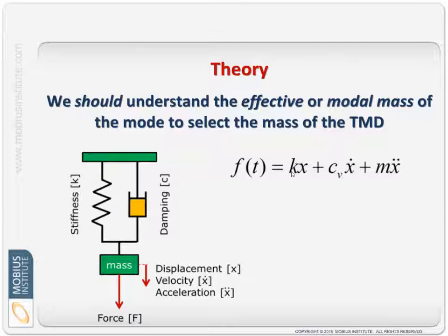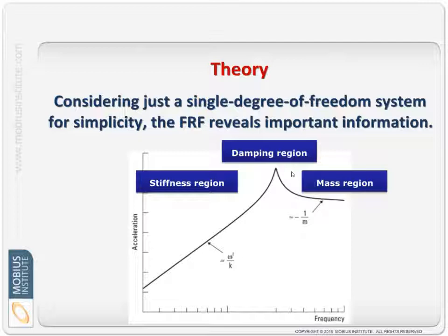And this is an important thing to understand. We'll spend much more time in the class looking at this, because if we're going to add one of these spring mass damper systems to a machine, we want to know what the modal mass is for that resonance.